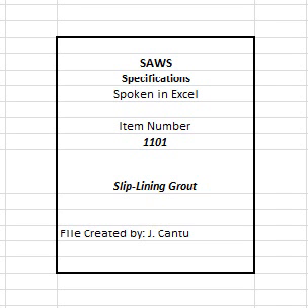The contractor shall notify the engineer of any changes to be made in grout, mix, grouting procedures, or installation. 2. Preparation. A. Notify the inspector at least 24 hours in advance of grouting operations. B. Select and operate grouting equipment and carry out procedures with sufficient safety and care to avoid damage to existing underground utilities and structures.